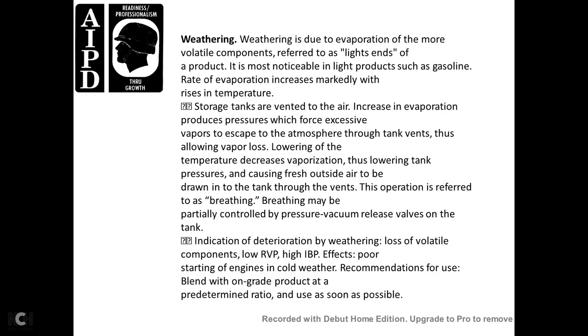Weathering is due to the evaporation of the more volatile components, referred to as the light ends of the product, and is most noticeable with light products such as gasoline. The rate of evaporation increases markedly with a rise in temperature. Storage tanks are vented to the air, so increased vapor pressure allows vapors to escape to the atmosphere through the tank vents, thus allowing vapor loss. Lowering the temperature decreases the vaporization and lowers the tank pressure, causing fresh air from outside to be drawn into the tank through the vents. This operation is referred to as breathing. Breathing may be controlled by pressure vacuum relief valves on the tank.